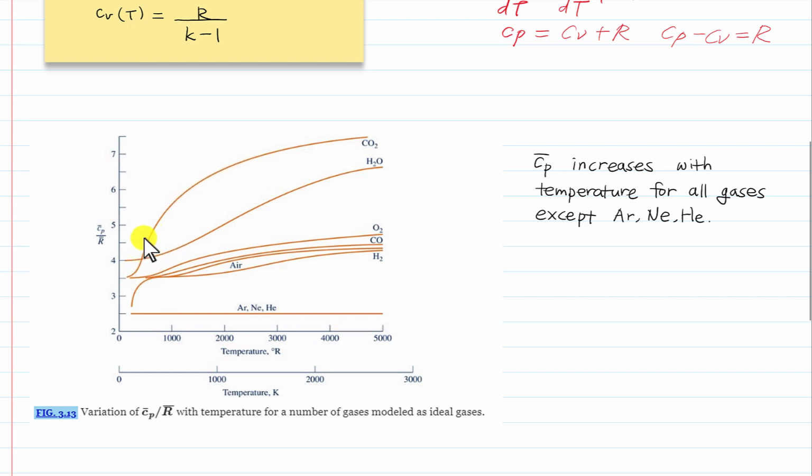The variations of specific heat for other gases is not large, especially within the small temperature change during a process. So we typically assume the specific heat is constant during a process and take the average specific heat in a certain temperature range.